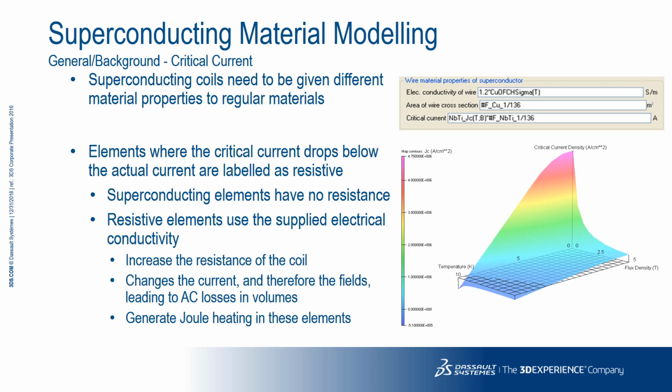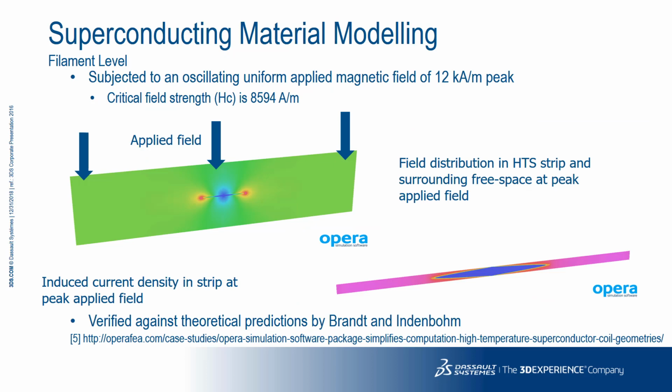Clearly, in a homogenized model, where the current flowing in the superconducting filaments is distributed equally in the volume fraction of the superconductor and matrix, the critical current density must also be diluted using this volume fraction to enable the bulk to transition correctly. If you're interested in validation of finite element methods for the simulation of an HTS material in an AC application, I'll mention this one test case.